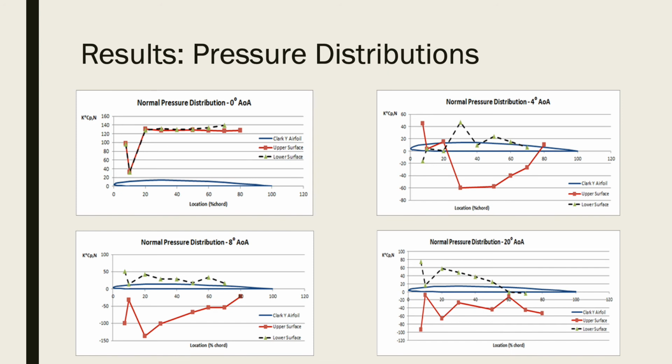At a high angle of attack, this pressure gradient begins to increase drag, and at 20 degrees, we can infer the effects of boundary layer separation at about 60% of the chord length when the pressures begin to match.